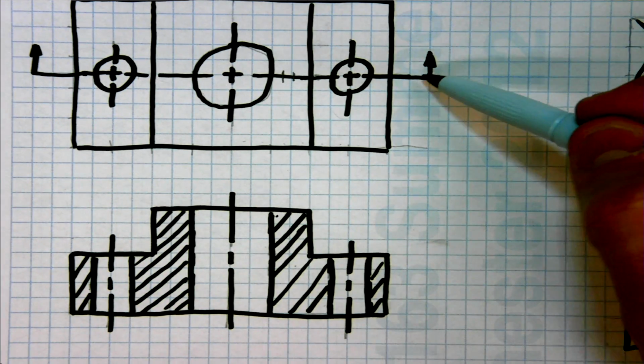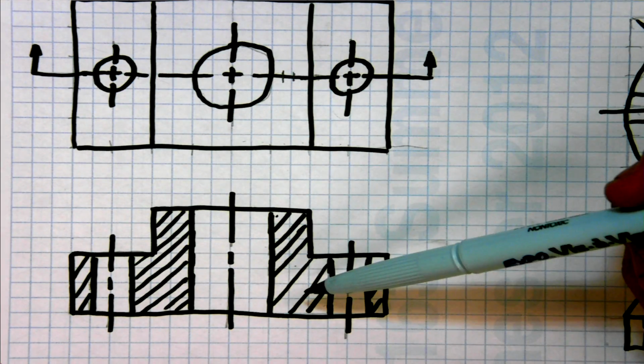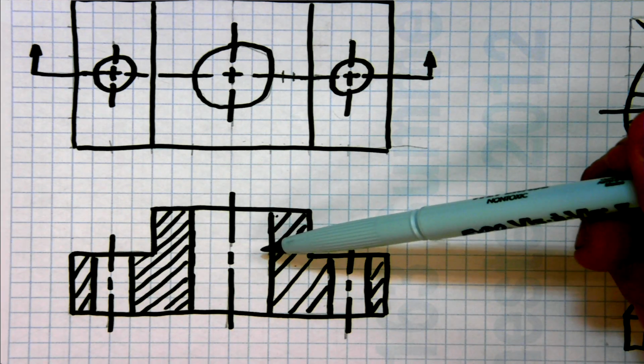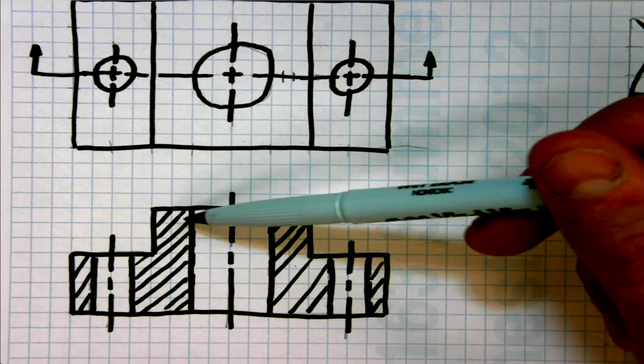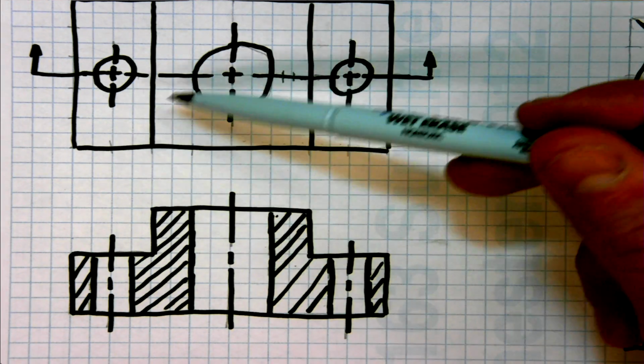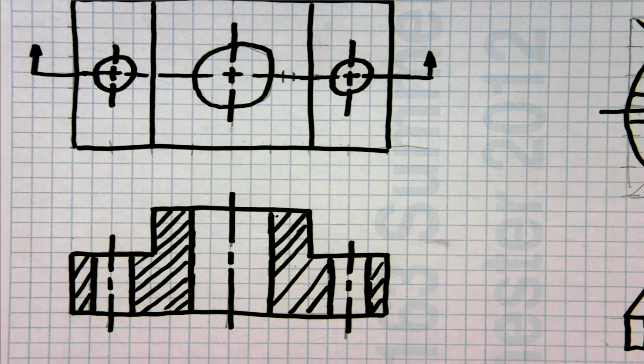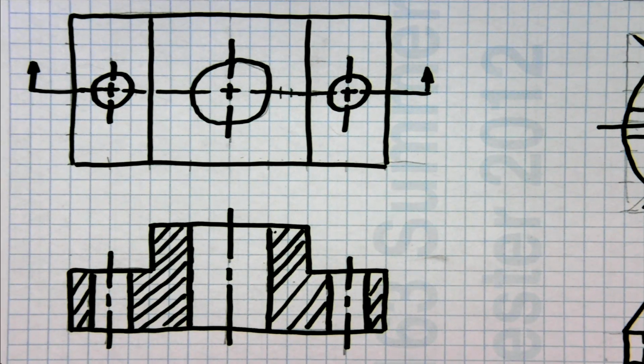So again, place the cutting plane in there. Visualize what's going to be cut. Anything that is not cut is airspace. Remember to put the lines behind the cutting plane because you still have material back there. And since these are all cylindrical parts, you still have to include the center lines representing the axis of the cylinder. So all that needs to be done on that particular one. I'll give you a chance to visualize that a second and look at it, and then we'll go to another one. Give you a few examples.